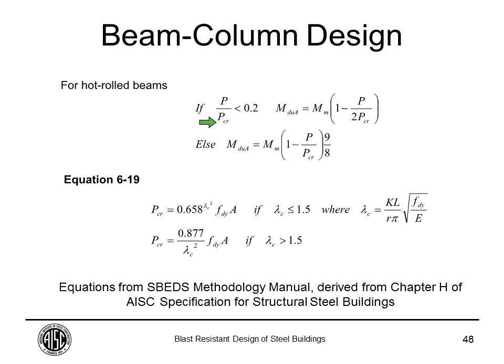Some DoD documents like the PDC TR-06-08 recommend you use 1 times D plus 0.35 L. The ASCE extreme load events recommend you use 1.2 D plus 0.5 L. Either way, it's a reduced load compared to the 1.2 D plus 1.6 L live load that you use in conventional design. And then again, these are the equations you solve for M, and that's your reduced moment capacity that you use to calculate your ultimate resistance in your single degree of freedom system.